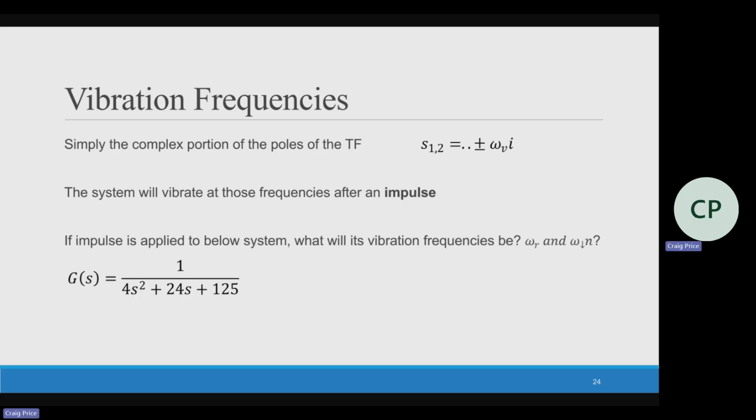It's got a little bit more damping, I think. Some of it's the connections. Obviously, we have materials, we have masses, there's connecting points. And so all of this system, we could model as one large piece where if I hit it with an impulse, I get this vibration frequency. So we can piece together a transfer function based on those roots.